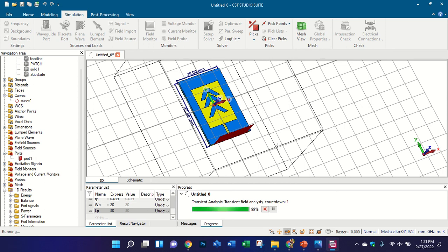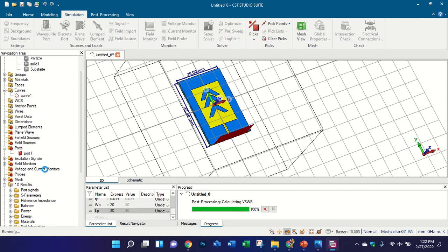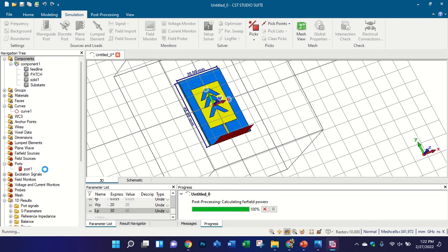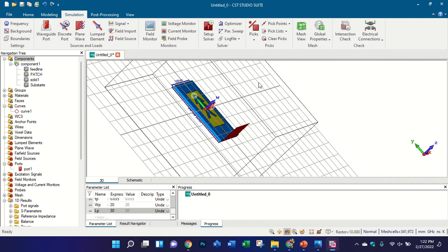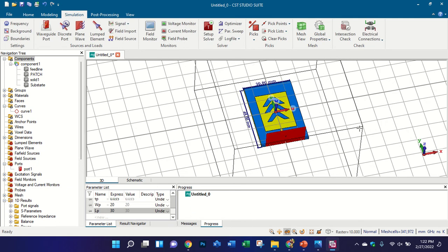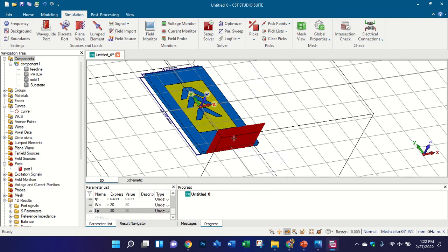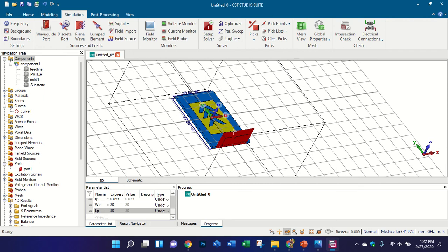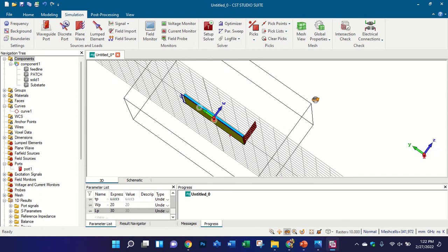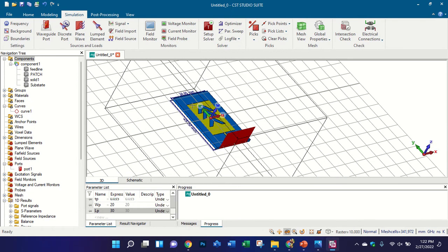Excuse me, sir. Sometimes when you reduce the ground plane, the radiation feedback from the patch to the ground increases, so the back radiation increases. Yes, it happens in most cases that if you are not using the full ground plane, then your antenna provides back radiation, which may harm your body, or if you are working on human body antennas. Also, in an antenna it is not acceptable to have back radiation. So you need to apply different techniques to control your radiation pattern.